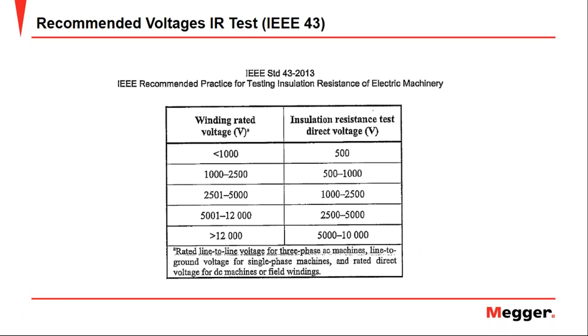When we are going to do the insulation resistance test, we have just stopped the motor. It was running in its application, and we stopped it, and we're going to do the insulation resistance test. The motor is obviously hot, and we don't have access to the winding. We do the temperature measurement in the case of the motor.